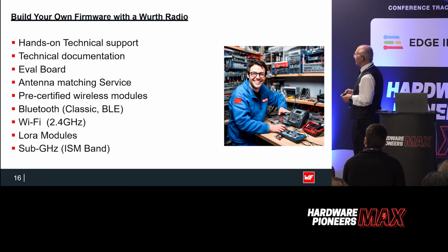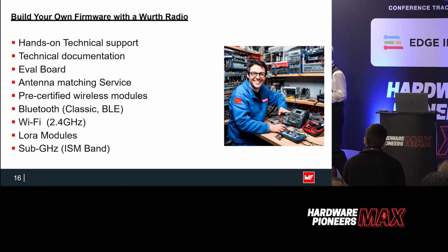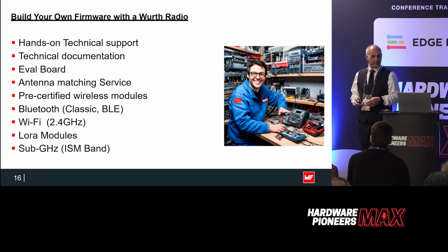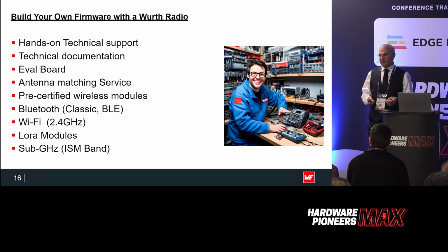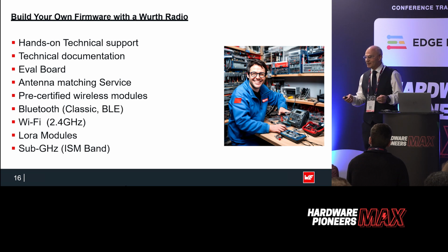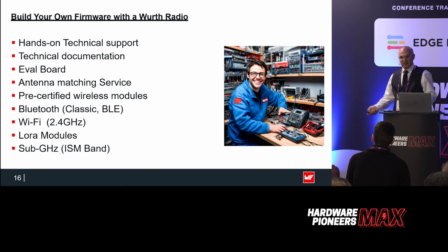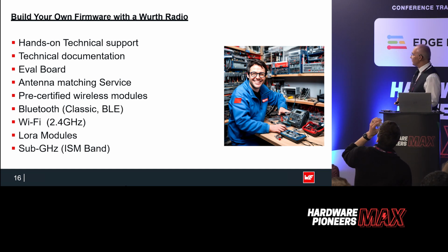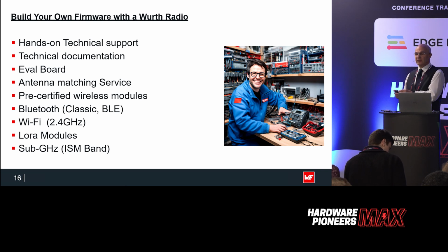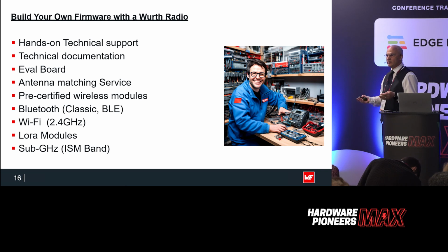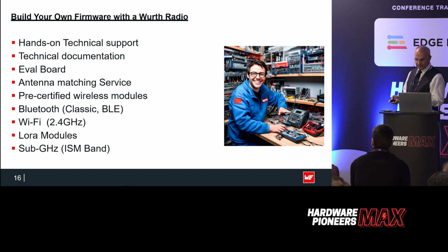And because we've got the pre-certified stacks, Bluetooth Classic, BLE, Wi-Fi, LoRa, and many sub-gigahertz ones, it might make it easier. There's no absolute certainty you'll pass, because if you've exceeded the duty cycles or the frequency or the power levels, it can affect it. But you're more likely to make it easier because we've taken into account the power supply requirements for the chip. We know the antenna is going to perform correctly. We're not going to have any spurious RF that's going to affect other equipment.